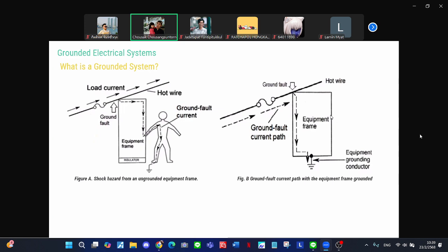In the normal production process, we have two kinds of ground. The first one is the safety ground that we are talking about. The other we call the ESD ground. The purpose of the ESD ground is to protect against ESD in the system. That is used to protect any equipment or part.